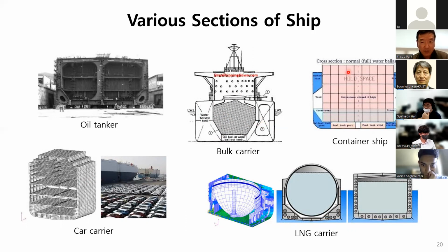A container ship has to have a big opening on the deck inevitably. So in this case, the thickness of plates for the smaller closed sections should be increased to maintain the rigidity of the overall section. An LNG carrier is similar to a container ship, with a big opening on the deck. So the design of the ship section is very important.